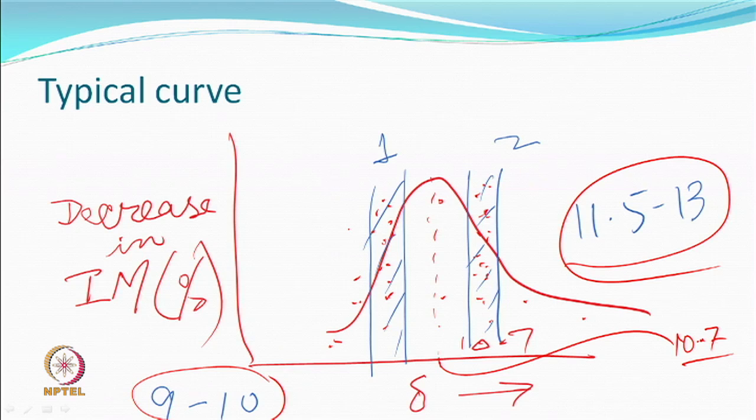One is an aliphatic segment, because of glycol, the other is an aromatic segment, because of phthalic acid. These segments vibrate and interact in different ways, so polyester by itself on average may have some value, but the segments interact differently because they are different in chemistry. Because when somebody says that only a segment of a molecule is going to work, which segment is actually interacting?